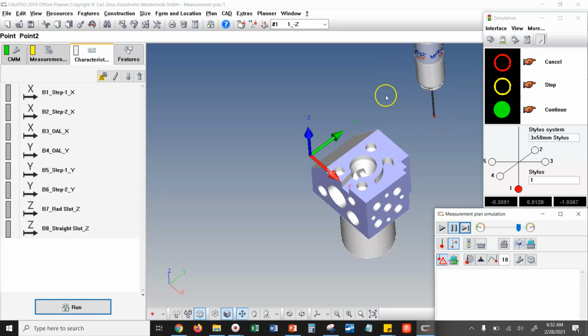All right, now notice this weird motion of the probe. It seems like it's coming over in the y-axis extra far. Notice how it came back extra far. That is that y-axis clearance plane. All right, this one has a z-axis clearance plane. That acts how we expect. And then this one has another weird one. This is an x-axis clearance plane.